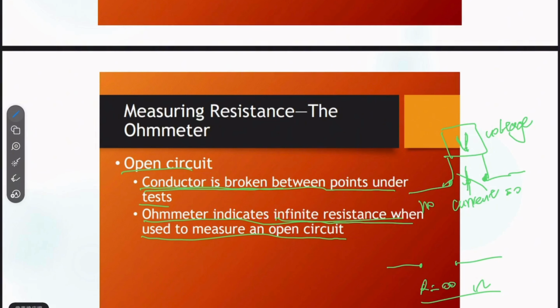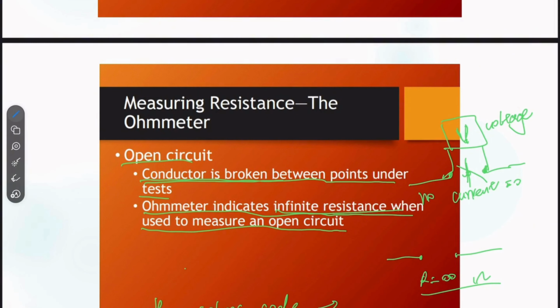That's kind of everything about the resistor. So we need to know the color codes. We need to convert the colors to numbers, then get the value for the resistance and Ohm's law. That's how we use the resistor in the circuit, and how we test the circuit when we have a short or open circuit.